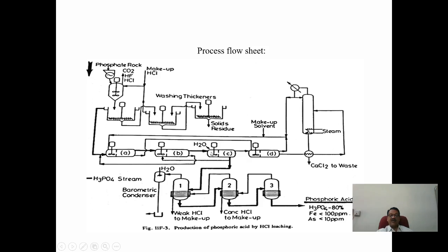So the hydrochloric acid is separated from phosphoric acid here, and the phosphoric acid is taken out and fed to a triple effect evaporator to separate the entrained hydrochloric acid vapors. Right. The calcium chloride slurry, which is formed in the reactors, flows from the first mixer settler to the last mixer settler, where it is washed and fed to a separator where calcium chloride is separated and discarded.